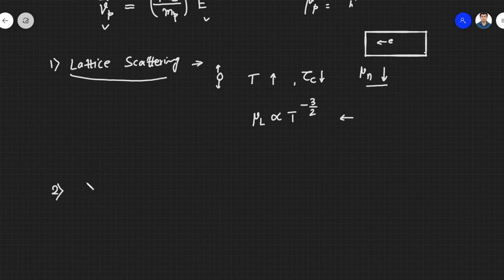So that comes into our second scattering. You will get the answer here now. You are absolutely right. At room temperature, in most semiconductors, as you increase temperature, mobility increases. But we'll see this because of the second factor we have, called impurity scattering. So let me write it, then we'll explain that. So it has two components: lattice scattering decreases the mobility, but impurity scattering increases it.